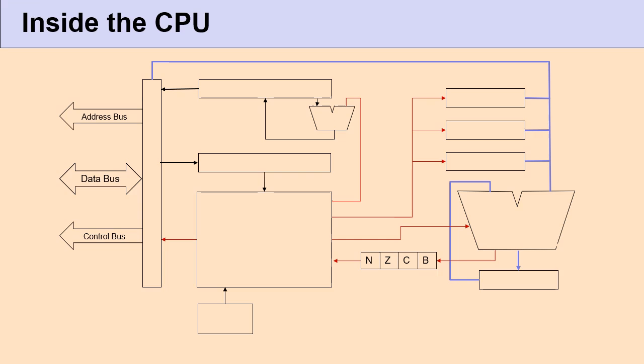And registers are there to hold data values temporarily, so that they can be routed to the ALU for operations whenever required. And some registers have special purposes, like the program counter and the instruction register, which are not used to store data but used to store other control information about the program.